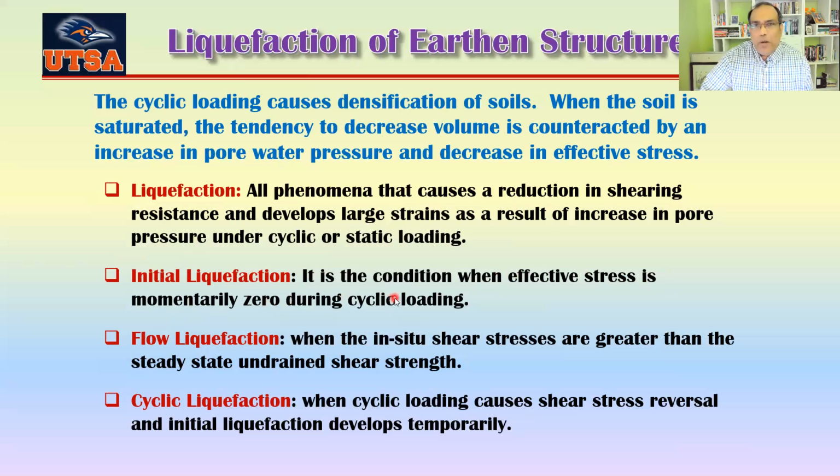The first time this occurs, when your pore water pressure is just equal to the total stress, or the pressure from the self-loading, the first time it achieves a pore water pressure at which the effective stress is zero, we call that initial liquefaction.